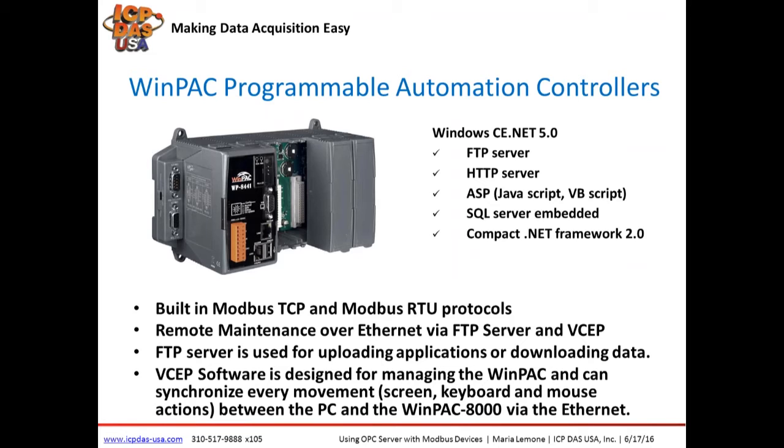The M7000 is Modbus RTU. The ET7000 series is Modbus TCP. We also have a PET series, which is power over Ethernet, so you can power them with our power over Ethernet switches. We also have PoE injectors, which can be used with regular switches.